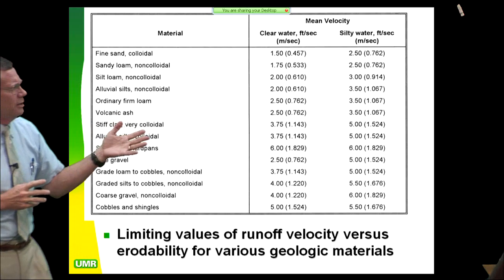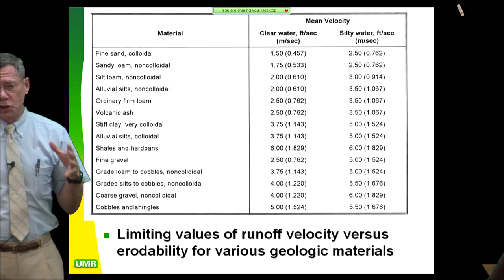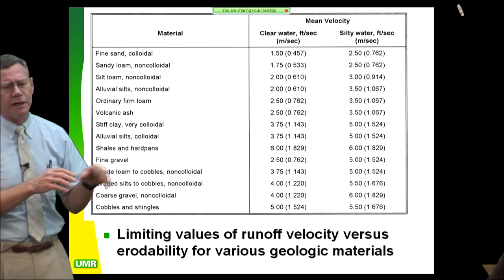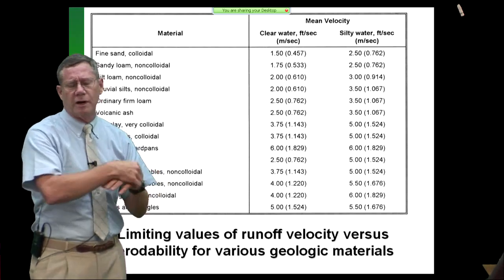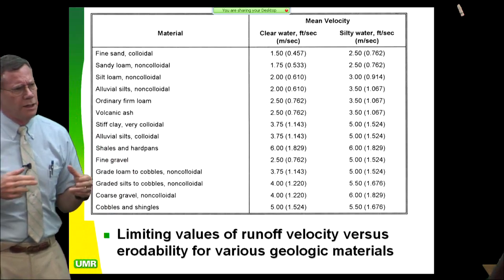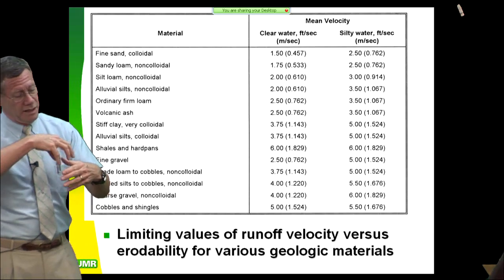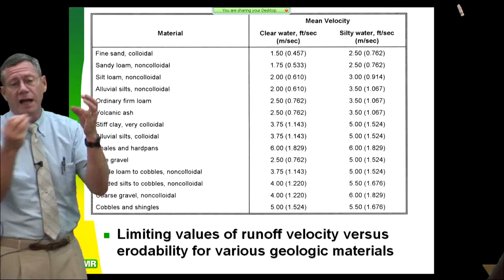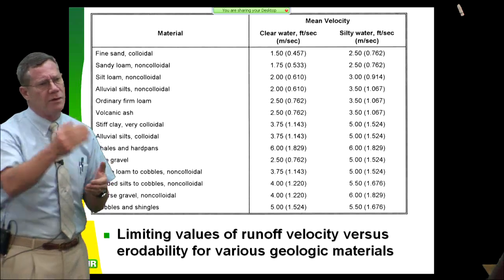And what this doesn't show is stream power. Stream power is the Q you're looking at, the quantity of flow and the duration. So the longer you have it moving there, the more things are going to start to move, transmit kinetic energy from one particle to another, and things are going to start coming unglued. Now when they start coming unglued, then you get roughness. You have places where it gets very, very rough, and you're going to get negative pore pressures and stuff poking out, and the erosion, once you get to that point, goes very, very rapidly.